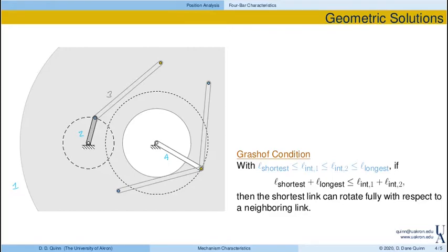Over here, I've connected link 3 to the end of link 2 and just put it in a random spot. Over here, I've connected link 3 to link 4 and put it in 2 different configurations. Now, the proper solution for this linkage is to bring this blue connection over to the end of link 2, right? So let's say that this is point A, and I have 2 different configurations depending on where link 3 and link 4 are.